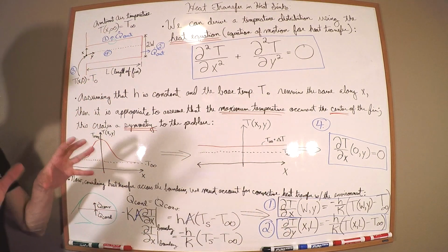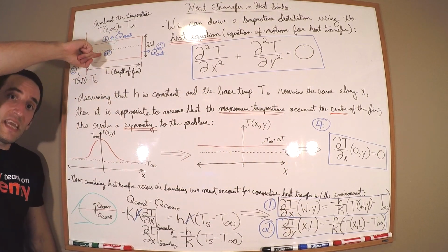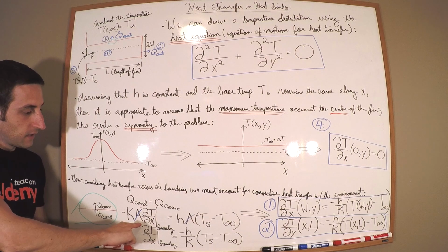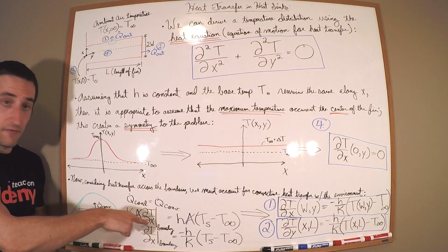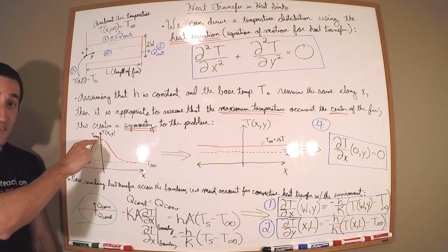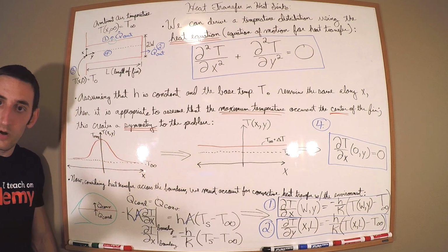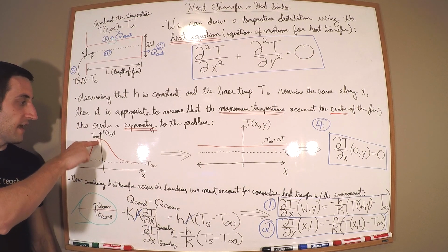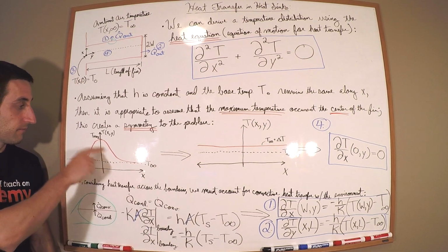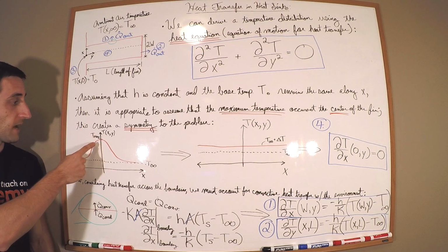So, the important thing to note, based upon this graph and what I said here, is that no heat flows through it, and that conduction has this derivative here, so dT/dx has to be 0. We can see it through the slope here. If we use Calc 101, right? This says dT/dx equals 0 when x equals 0, right?